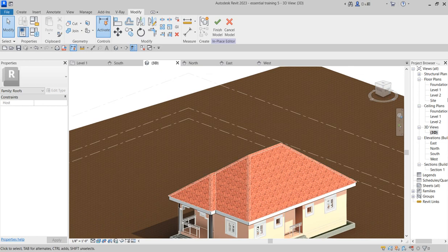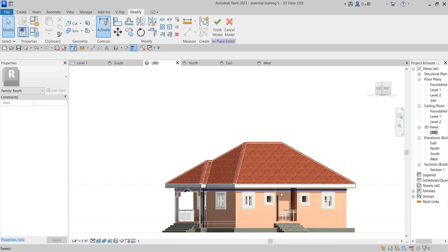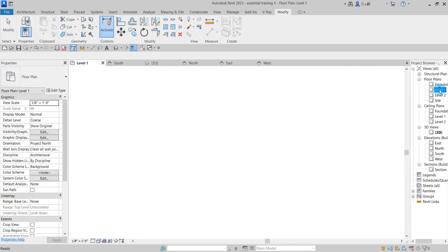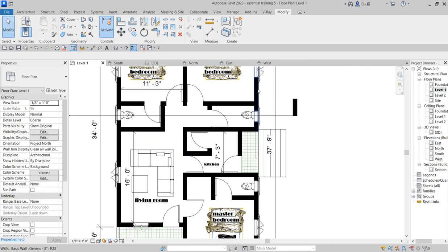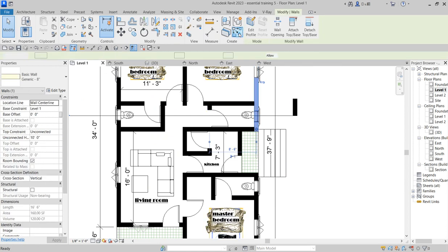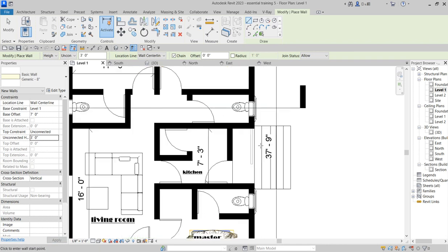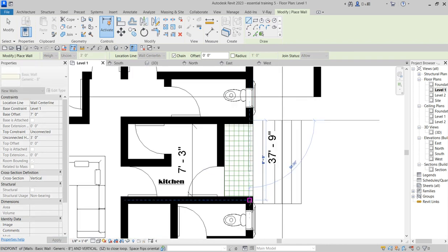So the half at the back, I want to work on that one because I don't like this. That space, this particular space is supposed not to be there. So click finish, then you go to your level 1. At the level 1 you click on this and say copy, create similar. From here you raise the standard up and say okay, let's say 7 feet offset. Then from here you use 3 feet. I say apply and you draw it from here to this point.